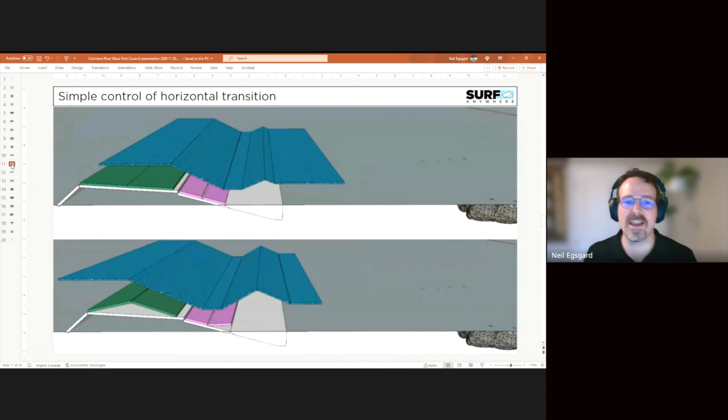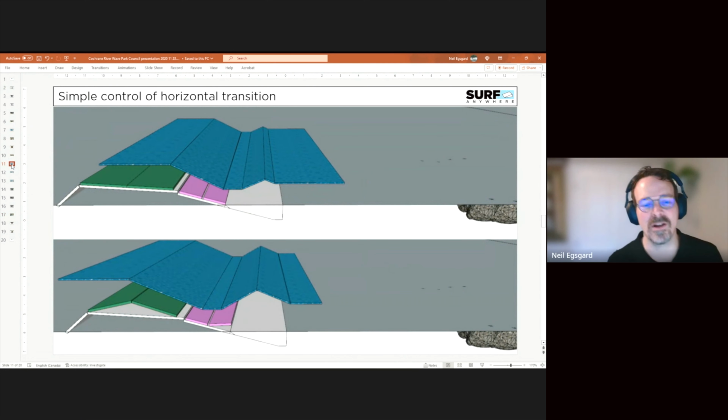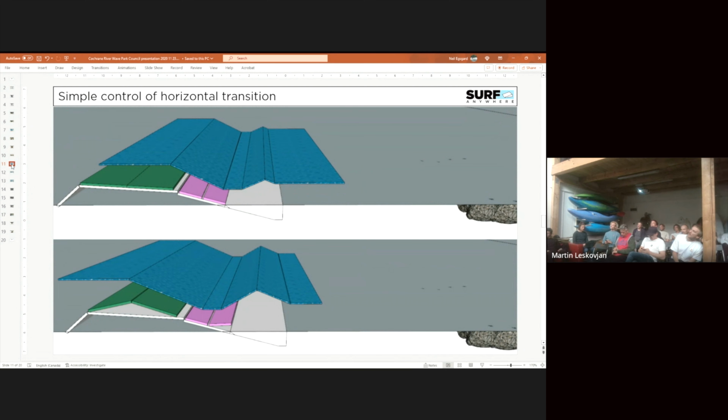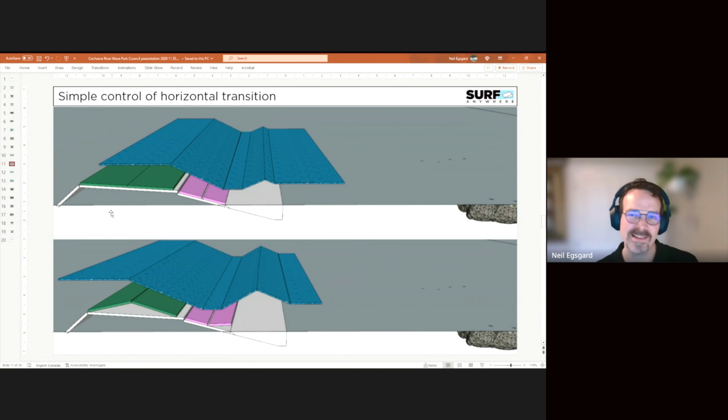Based on what we've been looking at on a few other locations, and what we just talked about, the concept that we're working on, currently in preliminary engineering and going to be doing the modeling for, has two main components. Let's say three. We have an adjustable gate at the top, which allows us to increase the drop during the low flow conditions, and also during really high flows, we can try to minimize the drop.